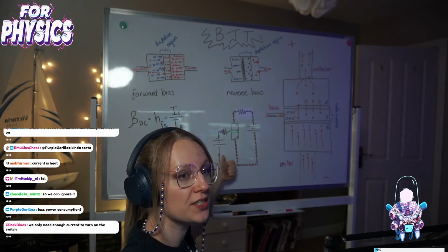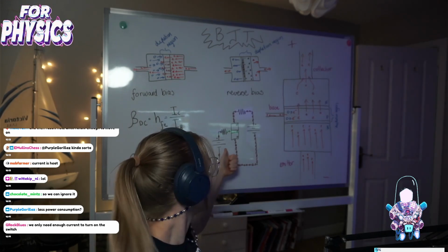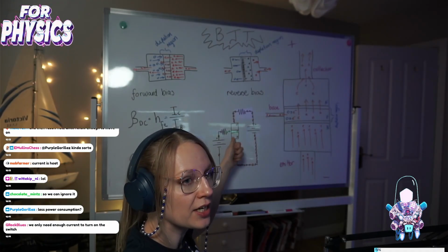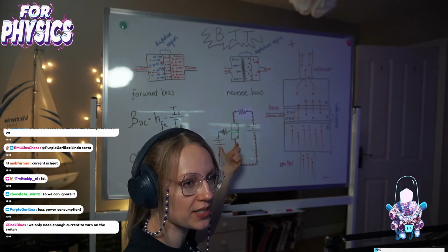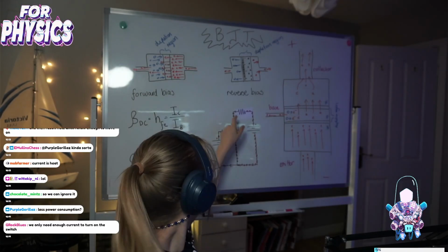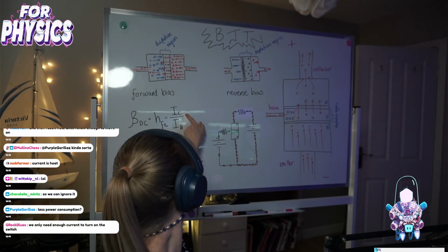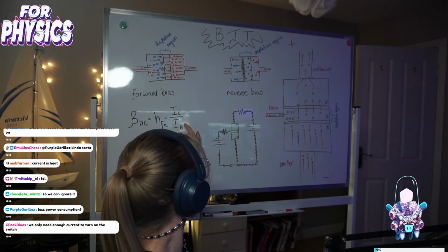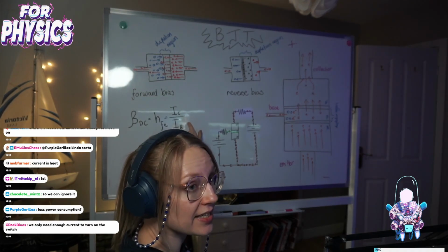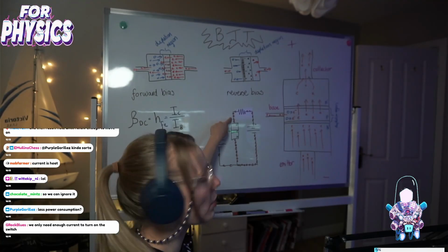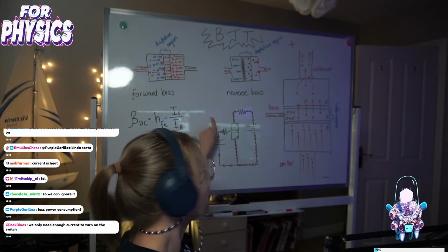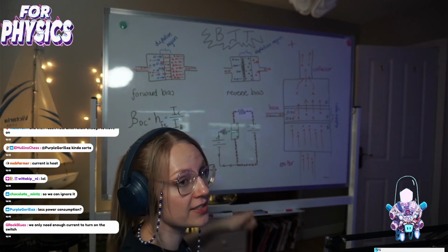This is a yes or no statement. And when it's yes, we want as much current in our system to be going through here. So it'll never be 100% efficient, but we want as much current as possible to go through here. So the collector current over the base current, that value should be as high as possible. Because this one number, we want it to be super, super big, and this one, we want super, super small. Big number divided by small number is equal to big number.